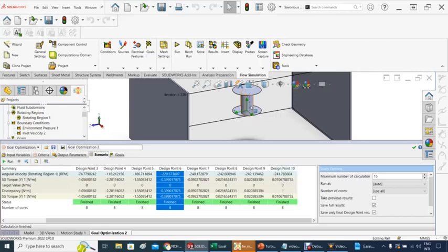In order to extract a good amount of energy, you want to look for the maximum torque somewhere here. It seems like that torque might be somewhere here. I would say maximum torque is happening here at about 116, which is very close to lambda of 1.1.